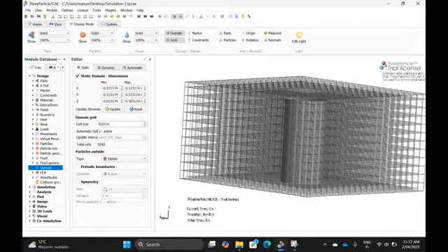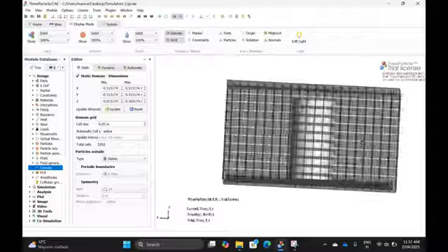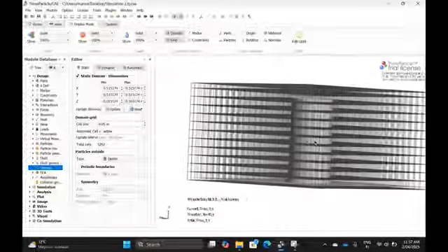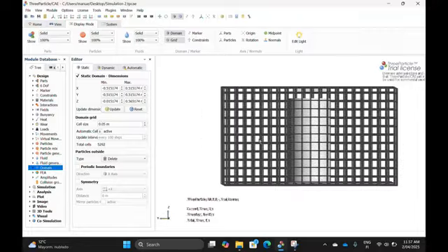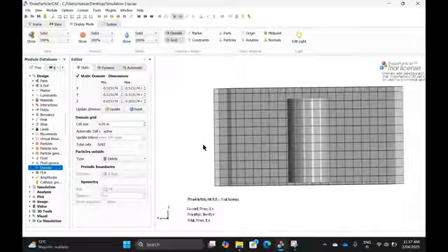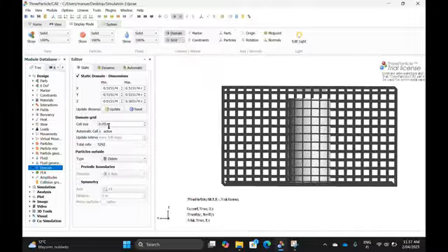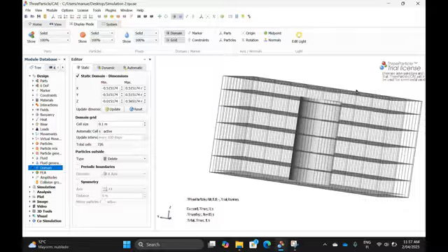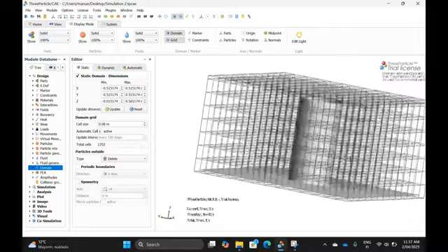I would stick with a value around the size of your particles, and I remember we have an outer diameter of 0.02, right? Something like that, or 5. So it's not that bad in that area. Probably a little bit smaller, something like that. A little bit more, because 1,000 is nothing. 1,500 still not that much. Let's see. But turn the grid off again. This one is important, so that all of our parts are inside of the domain. Otherwise, it most likely won't work. Save again. Call the simulation. And let's see if it's ready for run.